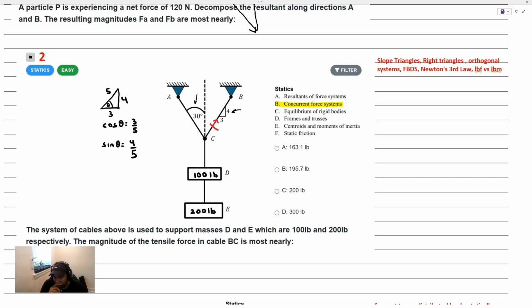The next thing is that in the upper problem, we were breaking it down into an arbitrary triangle. But in this problem, whenever we can, we want to break it down into a Cartesian system, the components of those forces, and apply Newton's law in the x and y direction. That's because orthogonal systems are like breaking everything up into right triangles. Right triangles are super simple to work with. No law of sines or cosines, just regular cosines and sines.